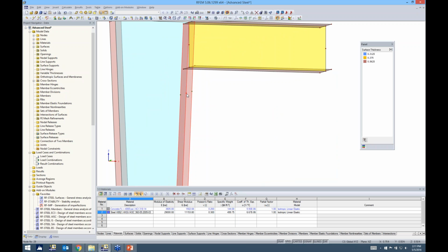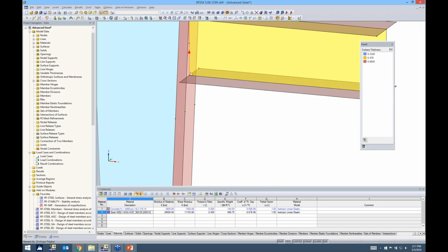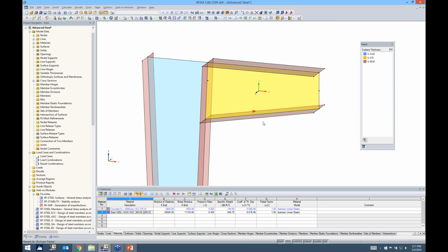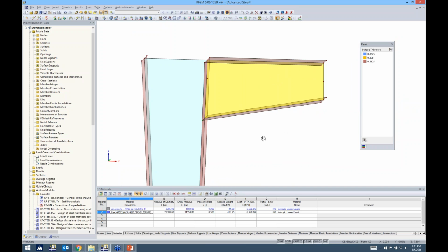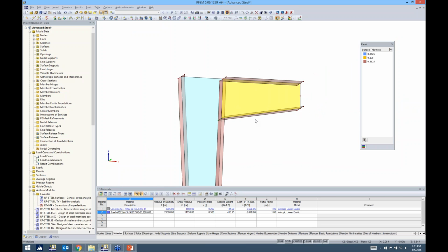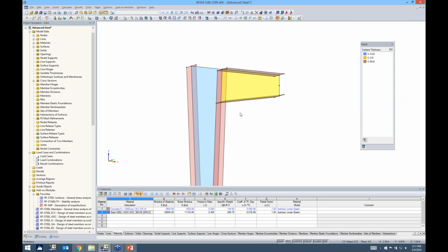So you can see this node was added here on the line, but nothing else has really changed. Now, holding down the control button again, I just need to highlight these nodes and then simply drag and drop. You can see that the program snaps to these nodes I just created, and we have a taper-like section. A leftover node was up here. I can just go ahead and delete that, and we have our 2 elements.